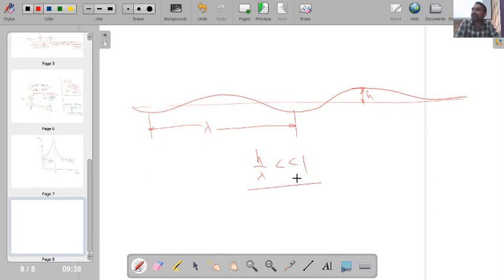And for this wavy surface, we applied the linearized subsonic theory, and then we tried to predict the value of Cp and other parameters. Okay. So now in place of subsonic, if I consider supersonic flow over this, say M infinity is greater than 1, and h by lambda is very small compared to 1, then it becomes a case of supersonic flow.